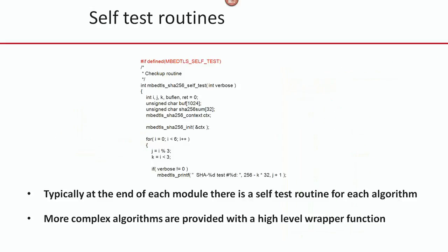If we look through the source code, typically at the end of a file there's a self-test routine with a hash define to enable it. So when you're trying to get the hang of using these components, there's usually a simple example that we can get working to test the algorithm before we start to use it and incorporate it into our code.